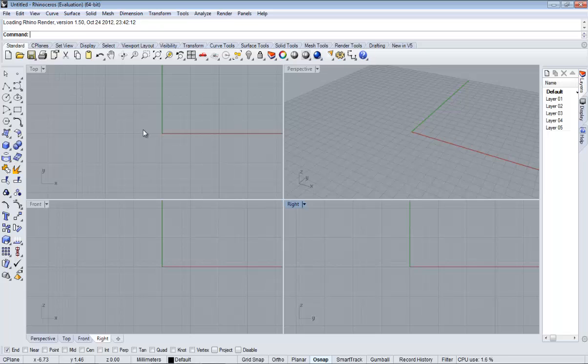The main thing you have to know is that there are 3 different ways of executing a command. A command is like a tool. We can use this menu, for instance, all these buttons here on the left. For instance, if I want to draw a line, you see here Polyline. So if I left click in there, now I'm using the Polyline command. Polyline is basically a line made of different lines, okay?